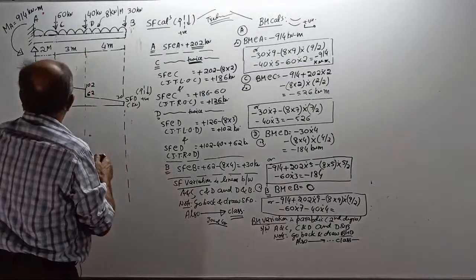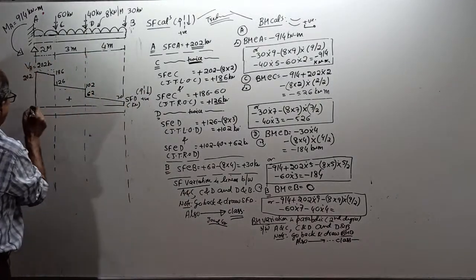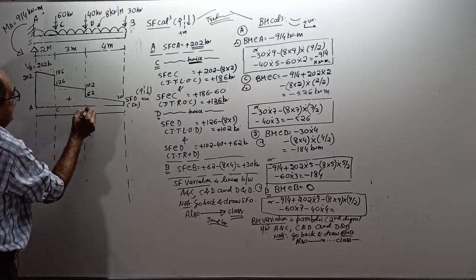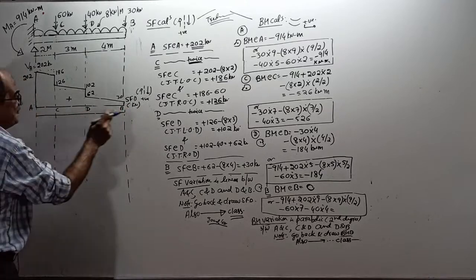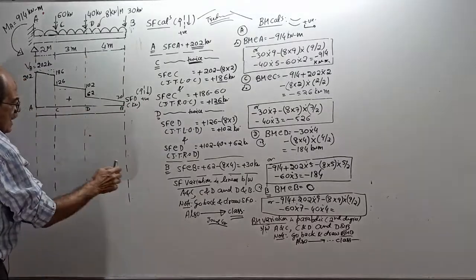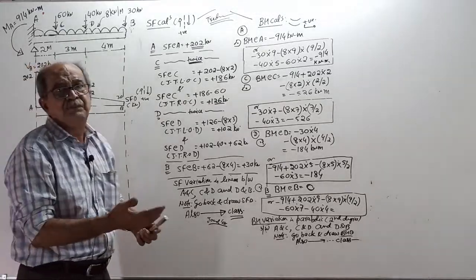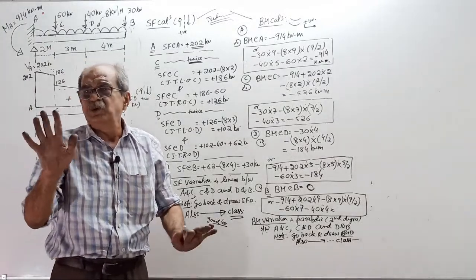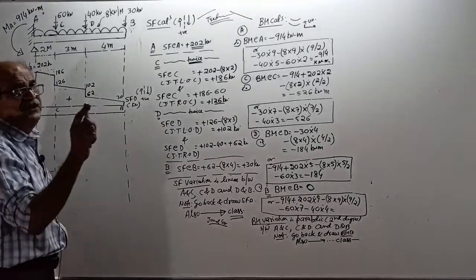Over. Now, see, this is the baseline for bending moment diagram. Point here A, this is C, this is D, this is B. Usually I put the baseline here, leaving space for upper side and lower side, both. If it is simply supported with usual loading, I put baseline here because I know full positive comes.